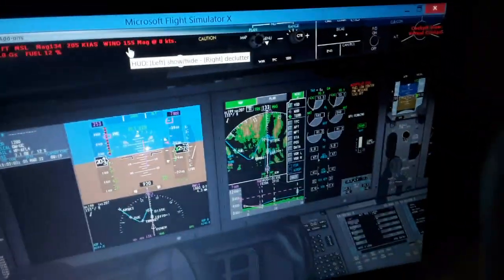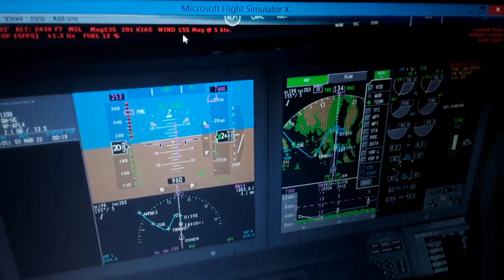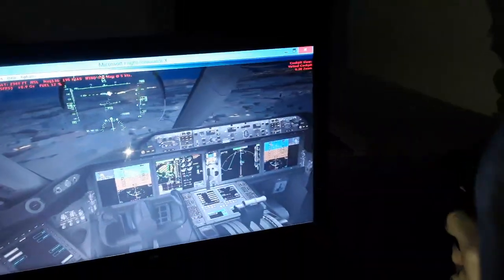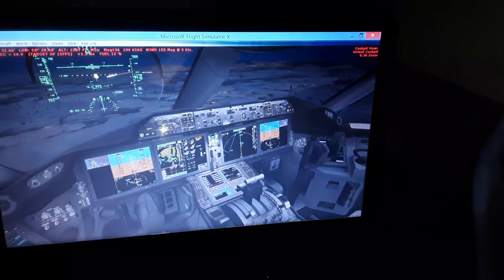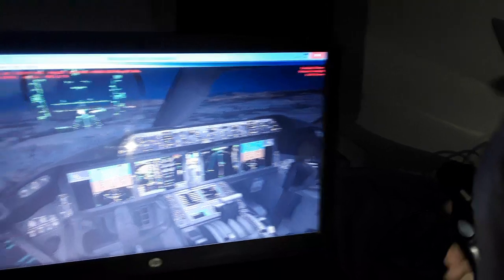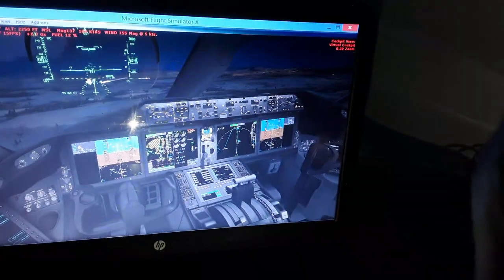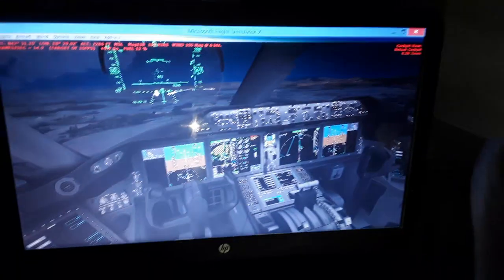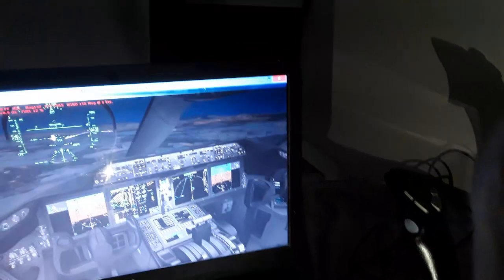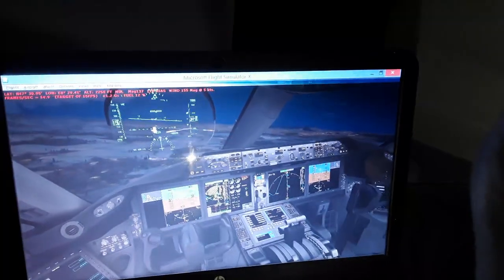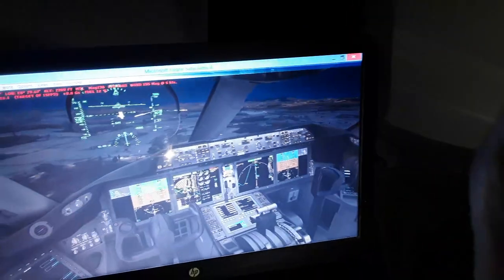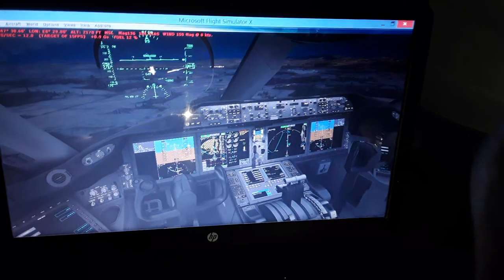As you can see all the information, the glide slope, we are below the glide slope. The altitude, the runway in front of us, so we can follow just the localizer if we have no visibility. Add a little bit of thrust, align with the vertical glide slope. Over here we need to go from white to red for this approach. So we have some side wind, we need to crab the aircraft with the rudder pedals. Here we have some side wind like this.